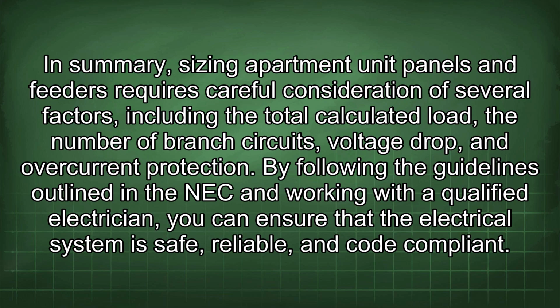In summary, sizing apartment unit panels and feeders requires careful consideration of several factors, including the total calculated load, the number of branch circuits, voltage drop, and overcurrent protection. By following the guidelines outlined in the NEC and working with a qualified electrician, you can ensure that the electrical system is safe, reliable, and code compliant.